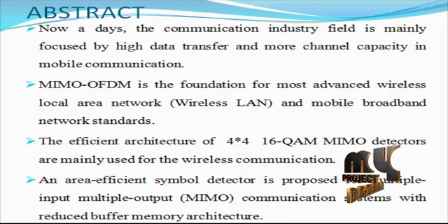initial estimate. An efficient high-throughput VLSI architecture is also introduced, achieving superior performance compared to the conventional MMSE detector with less than 28% added complexity. The performance of the proposed design is close to the existing maximum likelihood post-detection processing scheme, while resulting in significantly lower complexity for the overall equivalent MIMO detector architecture.